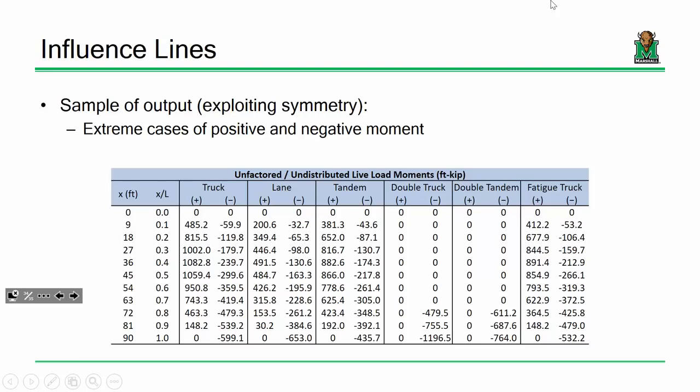Well, that's taking the tandem and maximizing it based on the influence line at that 9-foot mark. Now remember, the tandem is two 25 kip axles spaced at 4 feet. So, not square-centered, but probably one on the 9-foot and one on either side.